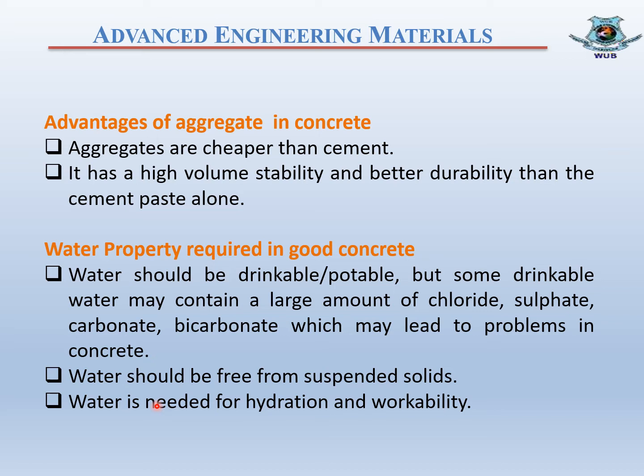In this regard, past performance of a particular source of water can be used to evaluate suitability of water. If not available, some testing is inevitable to evaluate water for setting time, compressive strength and durability.